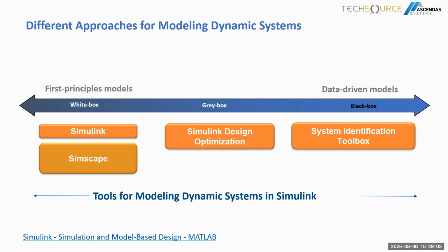And then from there, MATLAB and Simulink will be able to help you using system identification to actually calculate the system equation for your system. And then you will use all of these tools for your control system development. So that's how I am correlating power electronic conversion systems and adding it with the control system, so that you are able to fully develop a whole system if you are doing embedded systems for power conversion.